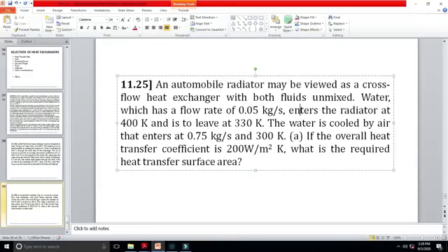is very extensive, and you would have seen that in 11-22 we had spent a good amount of time for the calculation of Hi. We first had calculated Reynolds number, and then we selected an expression of Nusselt number. We calculated the value of Nusselt number and equated it to hD over k. So if you go to LMTD, that may be quite extensive and quite lengthy.